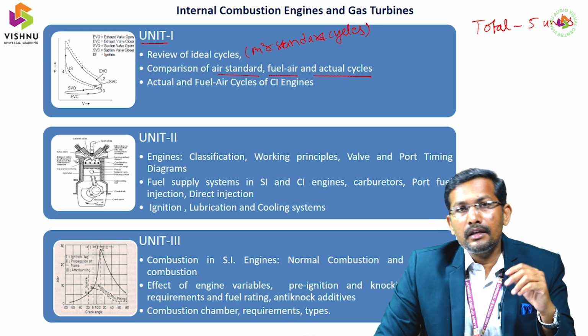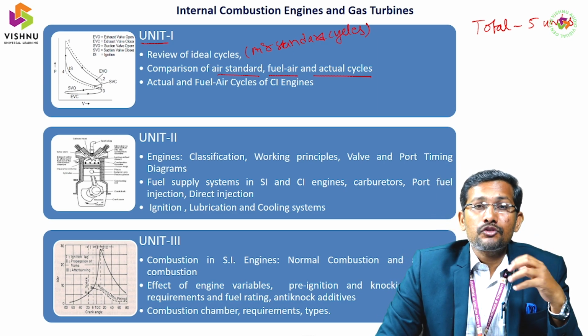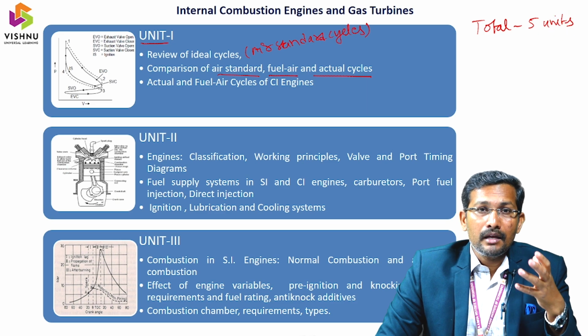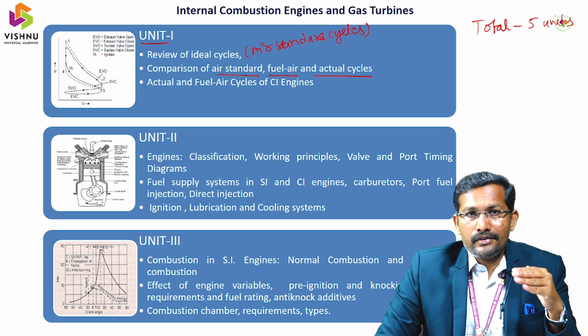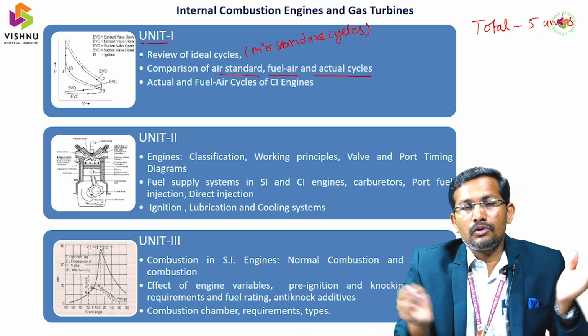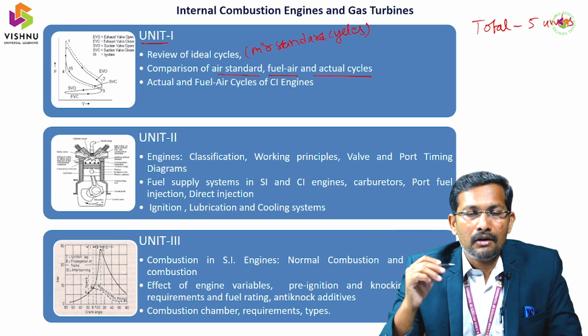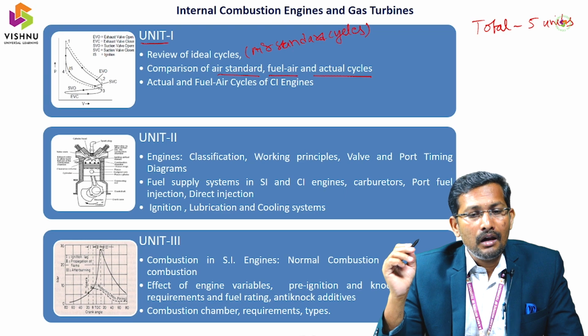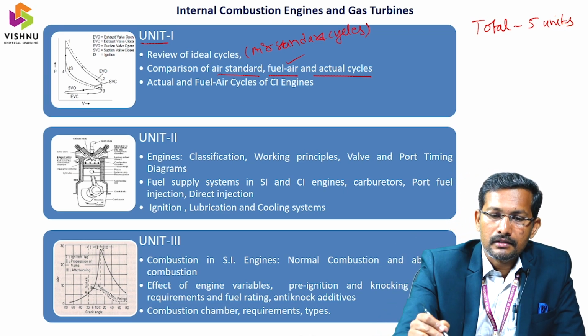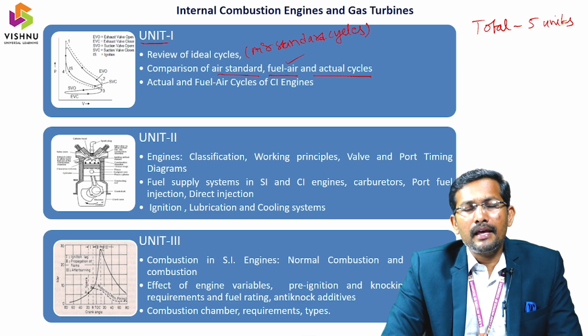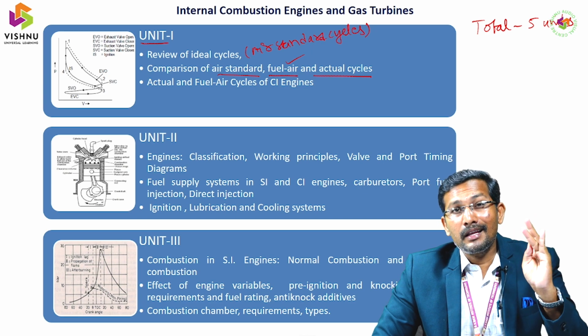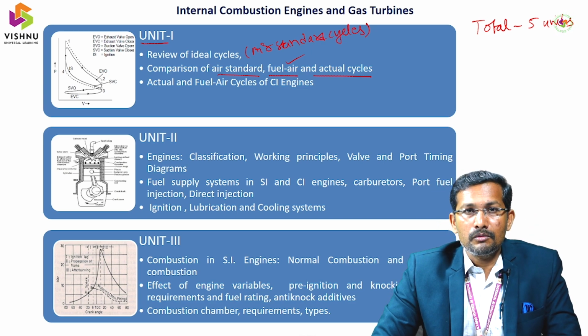Coming to fuel air cycles, we have the actual air fuel mixture, that means the real-time working fluid, inside air fuel combustion. But the processes like suction, compression, expansion, exhaust, to complete a cycle, total 4 processes will be there. All those processes will be reversible processes. That is one aspect in the fuel air cycles. And the second one is the actual cycles. In the actual cycle, we take a real-time working fluid, air fuel mixture, and real-time processes, reversible and irreversible.